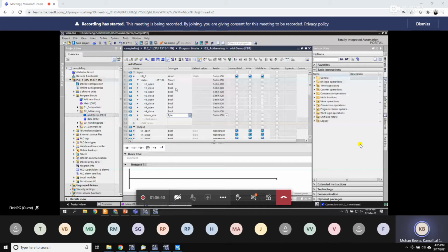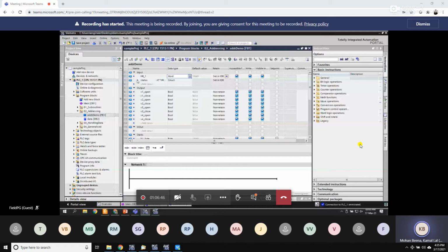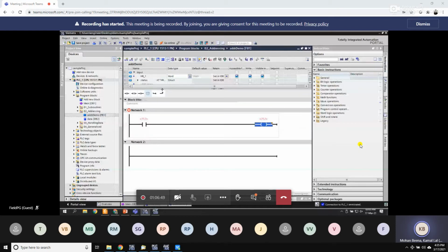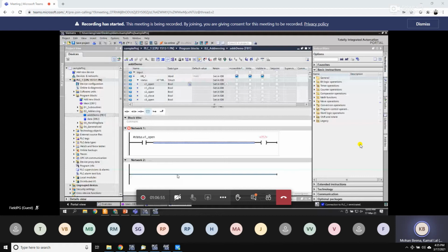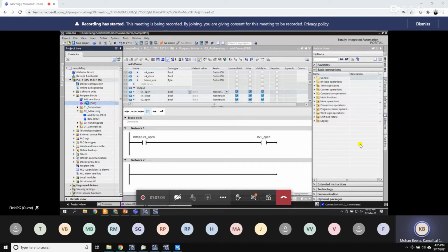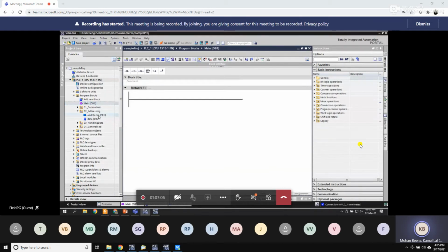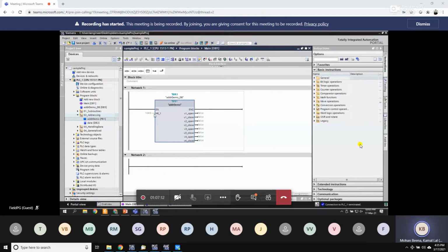Now, if I come down to my program, if you want to use it as an interlock for something, or in any of your program, you can directly make use of this. This can be given down to your output. Now, this does not mean that your block interface is changed. Up here, when I call this block, I am still giving a symbol, a word-sized holding register itself. Internally, I am slicing it, and on top of that, if I want to overlay other structures so that I can still have the possibility of symbolic access, I can make use of that.